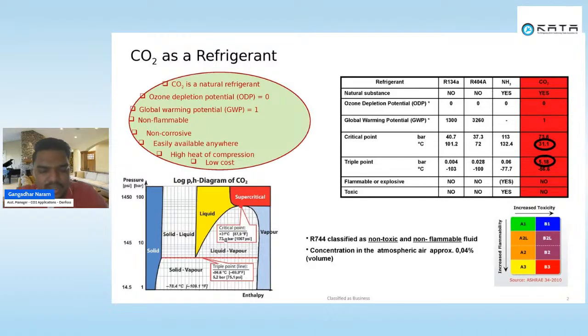Generally, all conventional refrigerants have a critical point higher than their condensing temperature. For example, if you take R404A refrigerant, the maximum condensing temperature goes up to 55 degrees centigrade. When it enters the condenser, it will desuperheat, after that there is a phase change, and after that it is subcooled. So a definite amount of phase change happens in the condenser, because for all the HFC refrigerants we deal with, and even ammonia, the critical point is always higher than the condensing temperatures.